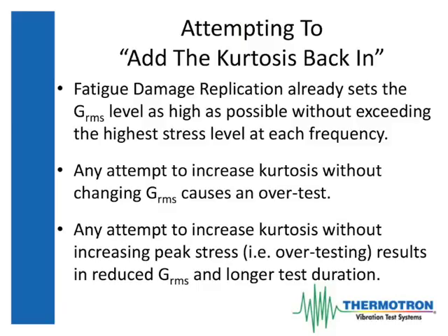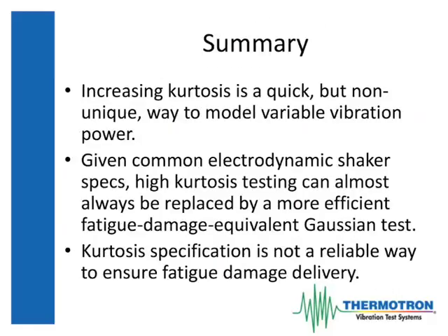So in a fairly one-to-one way, the degree to which you are willing to add kurtosis back in is the degree to which test duration doesn't matter to you. Now there may be reasons for that, but if your goal is to test quickly, this is never a good idea. So in summary, increasing kurtosis is a quick but non-unique way to model variable vibration power.